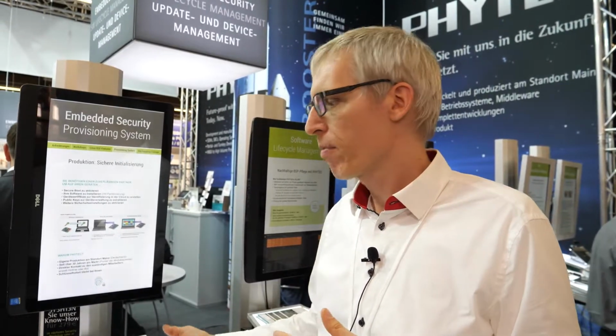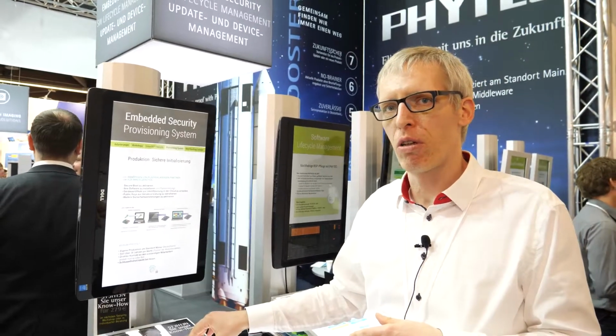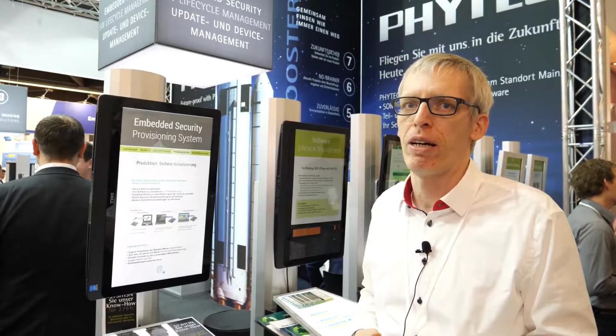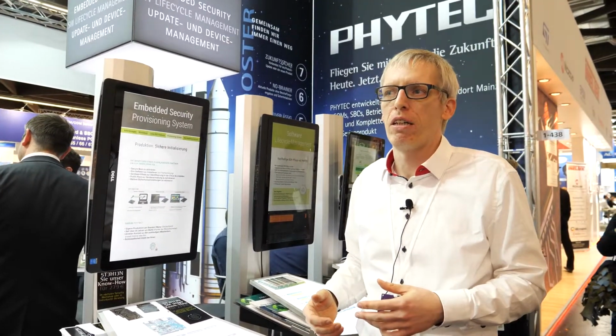We support external devices, for example, smart cards or TPMs too. But we prefer to use the features of the controller. For example, NXP has the NXP CAAM module. It has the same features as a TPM. So it's better to use it from the controller instead of an external device. But if you want or need to store more keys, it's better to use a smart card. And so you have a different key storage outside the flash and the controller.